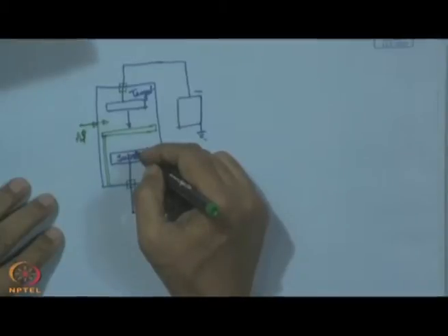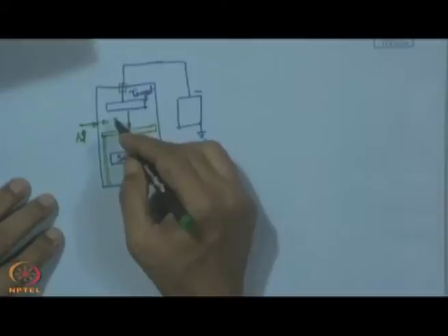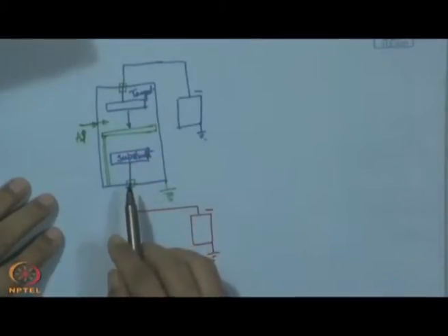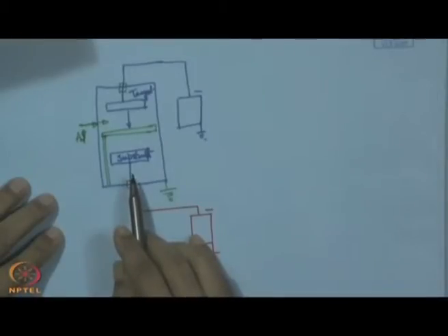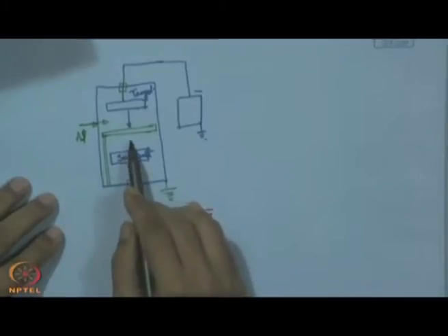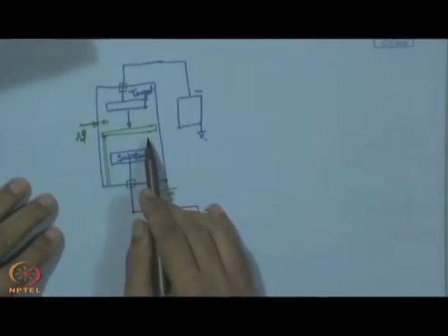Similarly, dislodgement of the substrate surface will also occur. In this process, any contaminant, impurity, oxide scale or any foreign material will be removed, and may be collected on both sides of the shutter plate, which can later be cleaned or replaced.